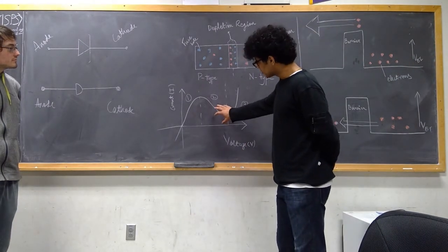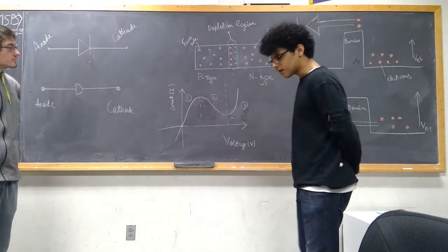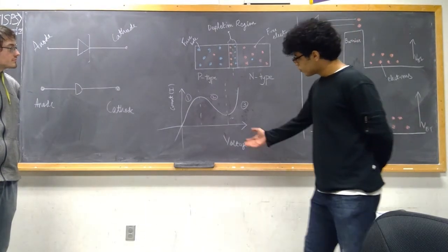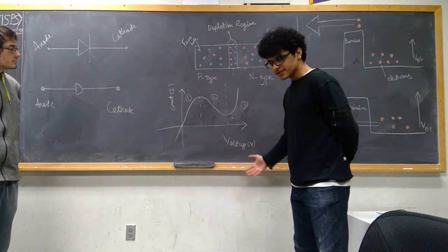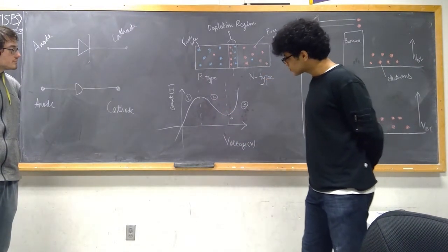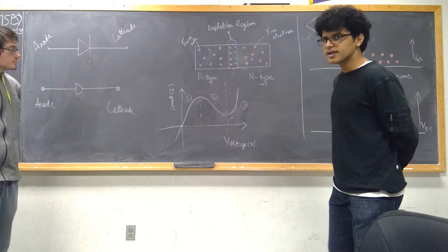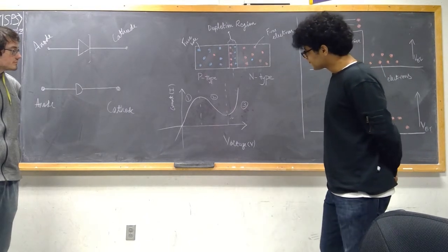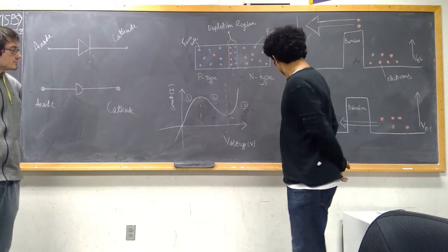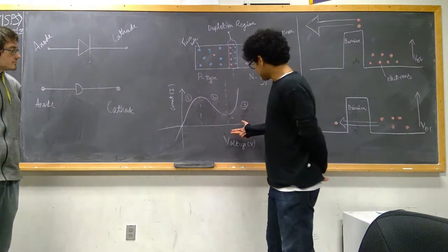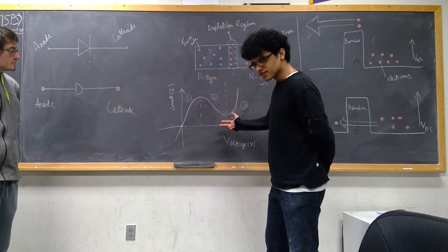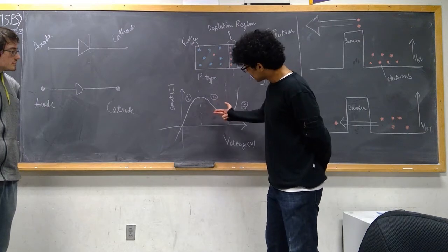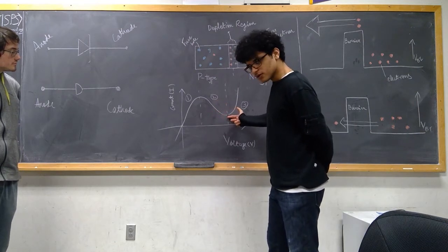This region is really unusual of an IV curve, as when one applies more voltage, the current through the device decreases. This happens because the tunneling diode offers a negative resistance. Now when we increase the voltage in this negative resistance region, the tunneling current will drop down to 0.